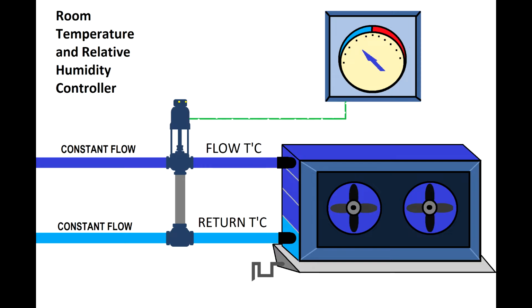If you have aggressive cooling and the heat exchanger gets just above zero, then it's obvious that you will run the coil below the dew point, and the moisture will condense onto this heat exchanger and then fall onto the drip tray. Now you can see it. The moisture from the air is condensing onto this heat exchanger, falls onto the drip tray, and is eliminated